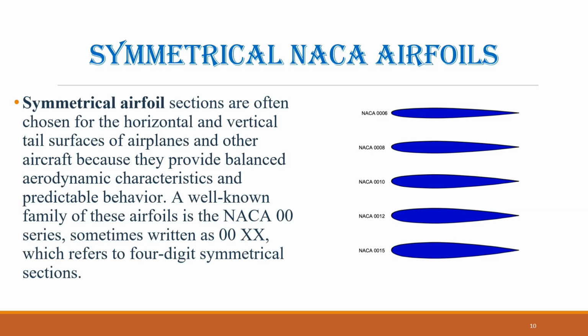The shape of the airfoil is defined in terms of its upper and lower surfaces, which mirror each other along the chord. The thickness of the airfoil at any point along the chord determines how fat or slim the profile is, and the thickness to chord ratio indicates the overall size of the airfoil relative to its chord length. For example, a NACA 0015 airfoil has a thickness equal to 15% of the chord.